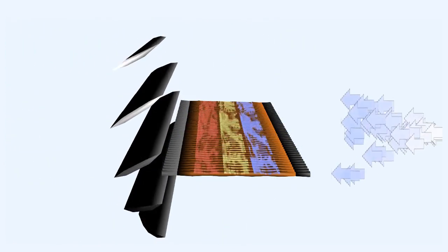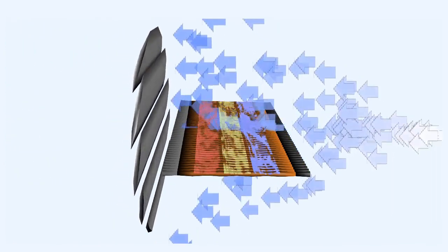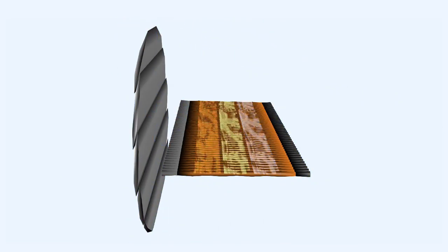The correct action to take would be to close the oil cooler shutters. If this is done soon enough, the heat of the oil in the core is passed outwards to oil in adjacent tubes in the matrix, lowering the viscosity of the oil sufficiently to start flow through the rest of the cooler, increasing the volume flow and thus eventually dropping the overall temperature of the oil contents.